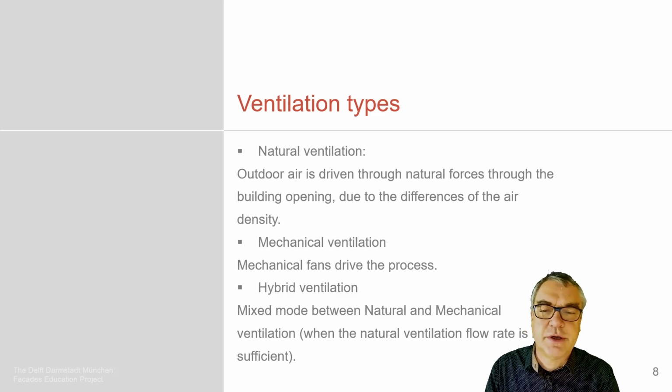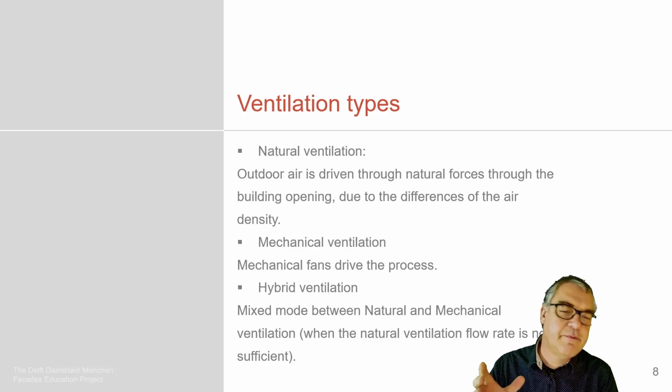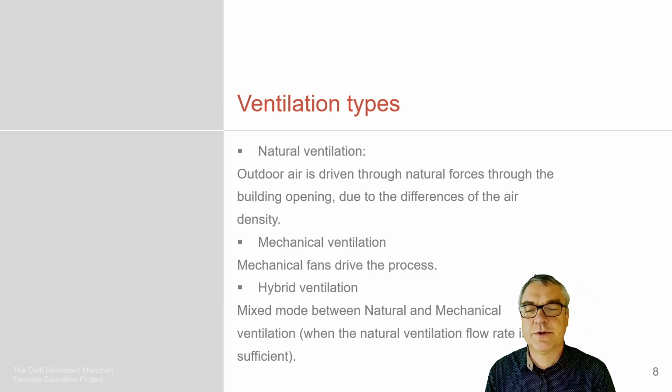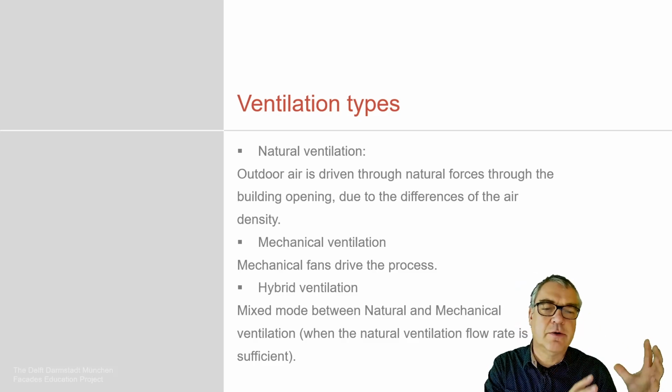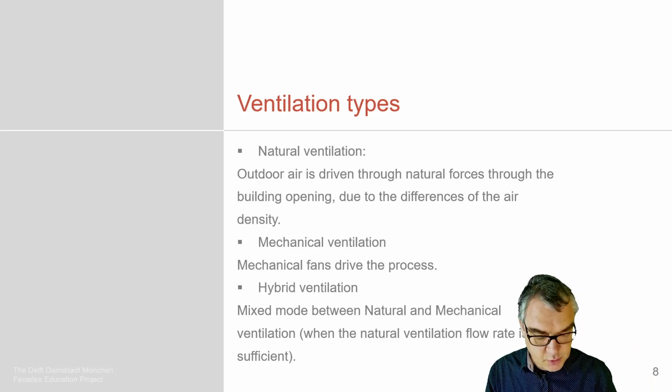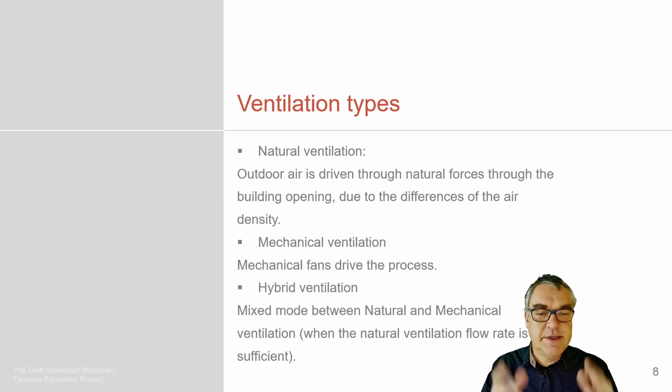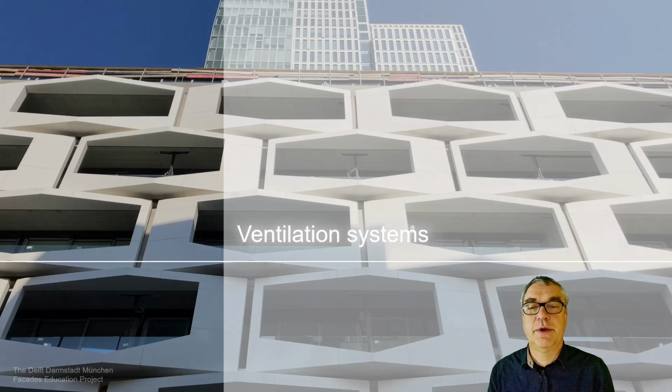Mechanical ventilation is a mechanical system which moves air via a fan through our system. And with hybrid solutions, you may have a chimney which exhausts with natural forces, but you may also need a fan to move air into the system. All this needs to be integrated into our building envelopes.